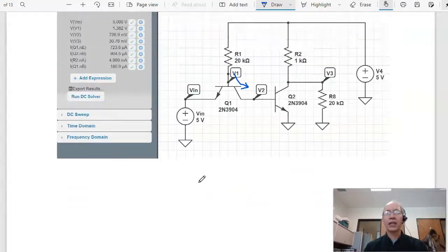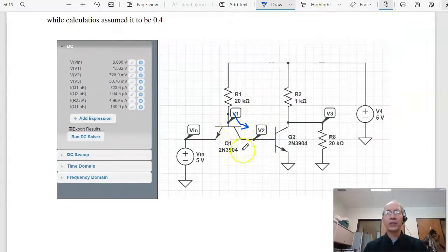And kind of a sidelight, I'm using a 3904 transistor. 3904s are not designed for TTL logic. If I built a gate, I could change the doping so that the gain would be 0.4 rather than 4. Less gain is good because less gain means less current being drawn from the source.